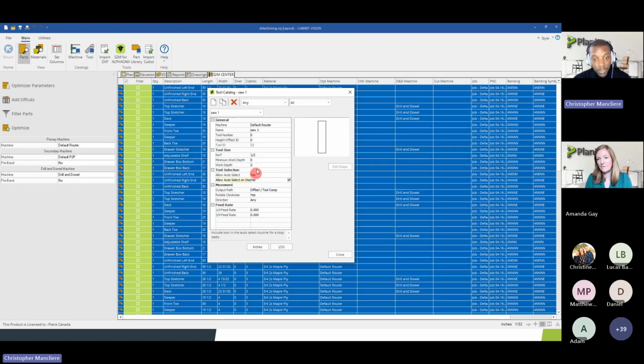The second thing is, of course, you want to set the feed rate and every other important setting. In your post processor, sometimes we also have to make a change to activate the saw depending on the machine. Some machines are seamless. With others we have to know what the saw number is and make sure that when we translate the CNC file to the machine, we also know what tool number this saw requires. And when it's a saw, you can also change the direction, so make sure you specify if you can cut in a specific direction, from left to right or any direction, for example. But the short answer is yes, it is possible.